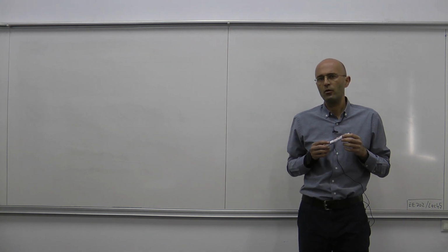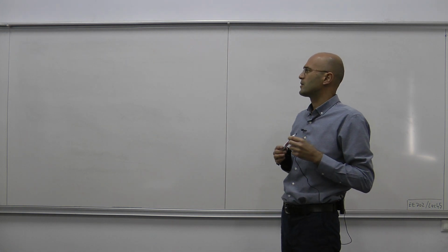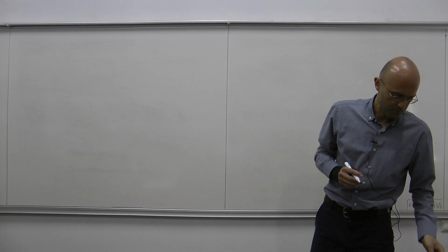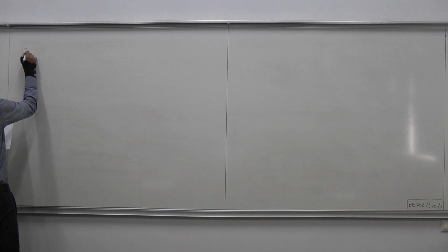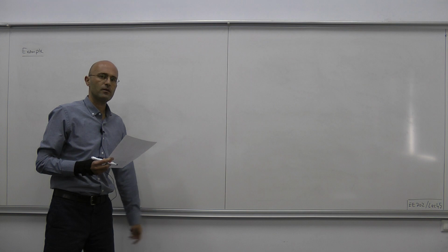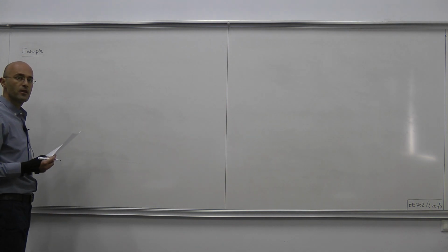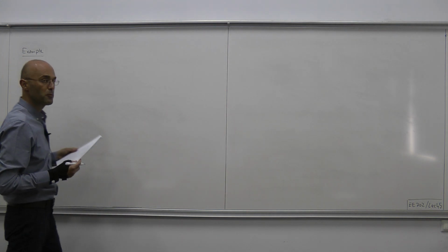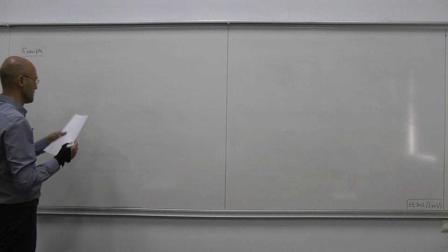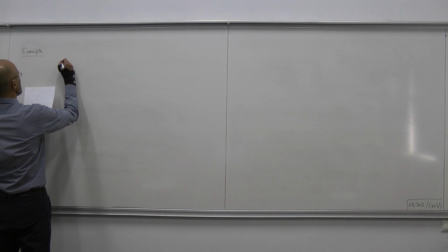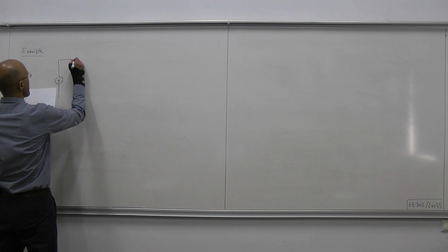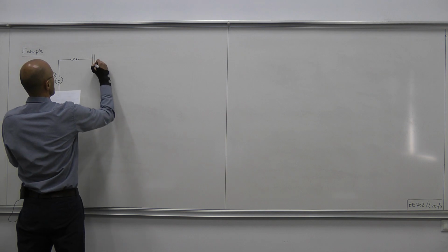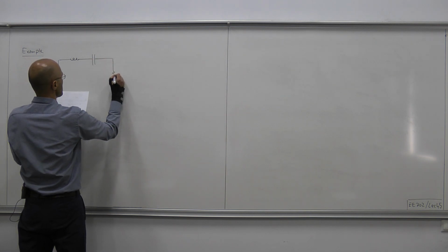In this lecture we will go through some second order filter examples. We begin by the same circuit that we considered in our previous lecture, but this time we will be collecting output from somewhere else. The circuit was a second order series RLC circuit.